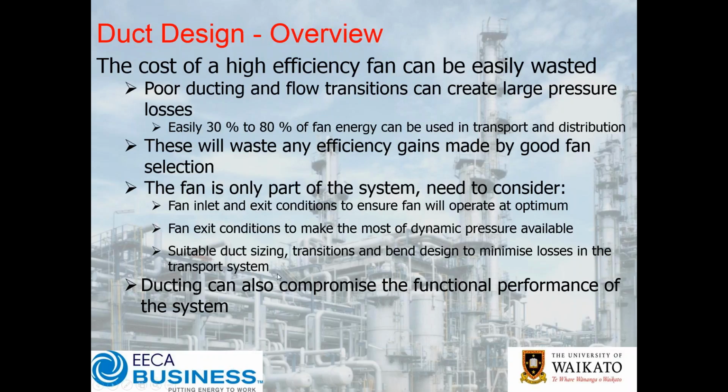Now, one of the key things with fan exit conditions is generally a fan generates quite a bit of dynamic pressure in the form of high velocity air coming out of the fan, and how well you convert that dynamic pressure or dynamic head back into static pressure is going to determine very much the efficiency of your fan in relation to the system and what it can do. Often we term that static pressure recovery. Now, suitable duct sizing, transitions and bend design can minimize these losses in a transport system.